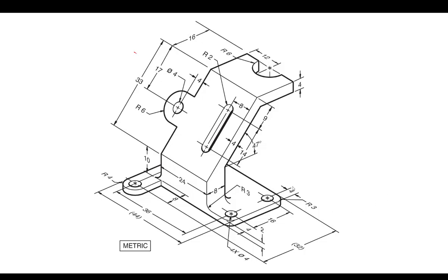Actually, looking at the right face here, what I see is this face right here is suited to be the first extrude. And that's because there's this face right here, which is not one of the standard faces. There's a feature on it that if I'd like to capture that, it's best if I don't have to build construction geometry planes, it's best if that plane exists after this extrusion, which it would. So I'm going to extrude this as my first extrusion.